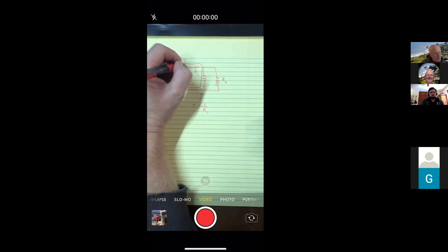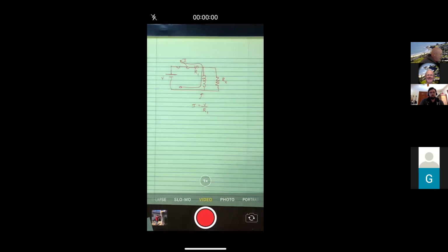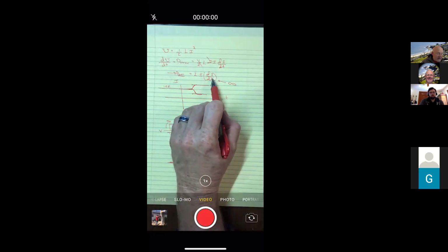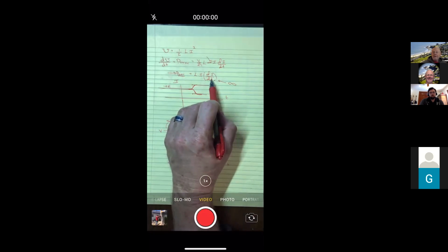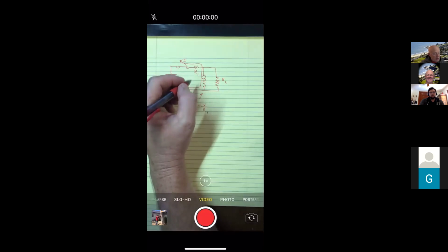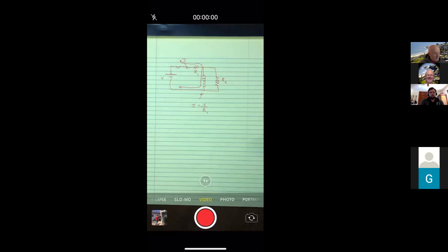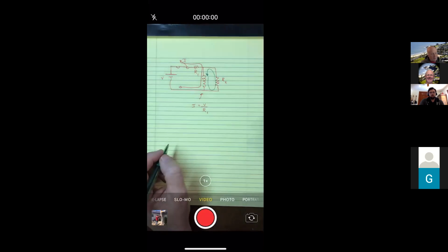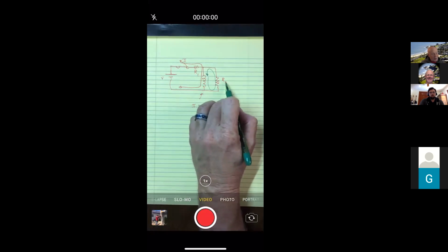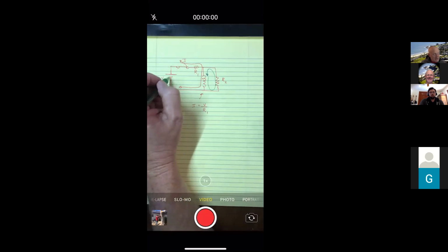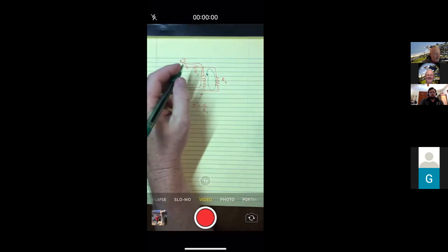And then if you open the switch, I'm going to come back to this statement. It's not a statement that says the current has to stay at 0. It's a statement that says the current has to be a continuous changing function. So when you open this switch, the current now will start to do this loop. And it will start to go through resistor number 2 and decay away once you've opened this. This battery is now out of the circuit, if you will.